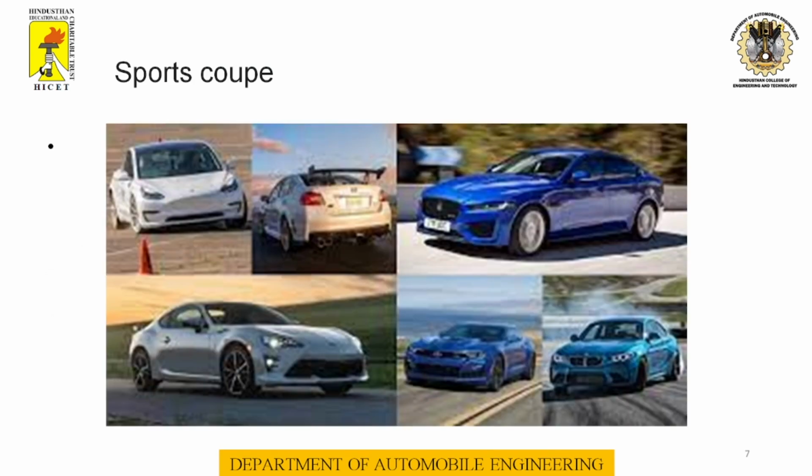Next, sports coupe. It is basically a small car with 2 seats. Better aerodynamic shape and better acceleration are the features of this model. Styling is not important. At the same time, lightness and rigidity are also features of this model. In this model, the drag coefficient considered is 0.2 to 0.3. Coupe is similar to sports coupe, but with 2 extra seats at the back and hence can be used as a small family car. So this is a sample picture of sports model cars.